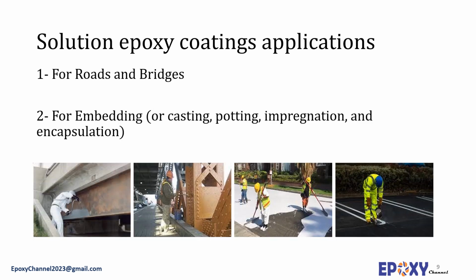Epoxy resin coatings have been successfully used to protect and repair road and bridge surfaces, where the combination and accumulation of many different factors such as freeze-thaw cycles, spillage by vehicles, road greasing, etc. can cause defects in the surface. For these conditions, usually liquid epoxies, coal tar extenders, and amine hardeners at ambient temperature are used.